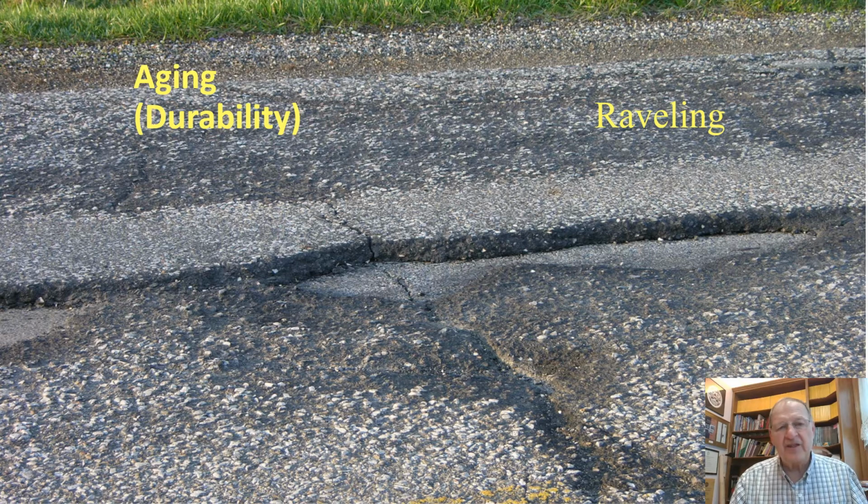And then all of a sudden, in the course of one late winter, early spring, the wearing course completely unraveled. Essentially what's happening is the low asphalt content allowed the oxygen to get in and age the asphalt binder. When it was aged sufficiently, then rocks started to get dislodged. And as soon as one or two rocks started to dislodge, adjacent rocks could easily be torn out by the traffic traveling over it.